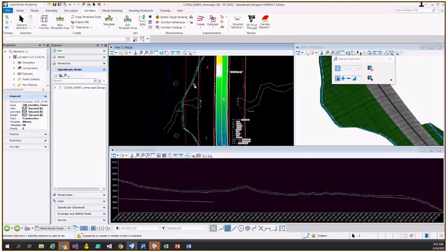And then we're going to make our modifications as needed and then project that onto our center line and remove the rules. That way it'll stay. And then we'll switch our template back, and then we'll do a point control to control that ditch vertically to our ditch profile. And that way you'll see that our foreslope doesn't get destroyed in that process, so we keep our foreslope to what we wanted it to be.